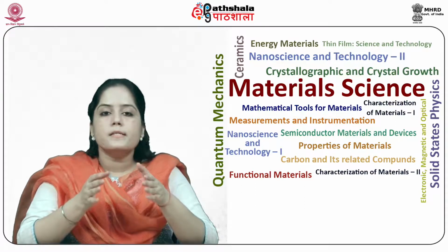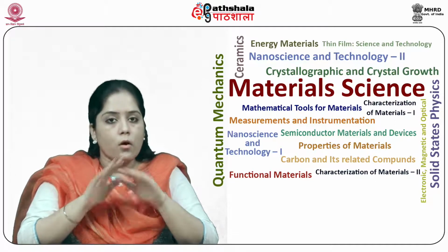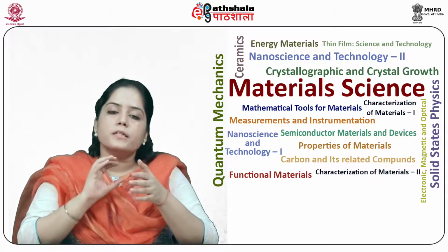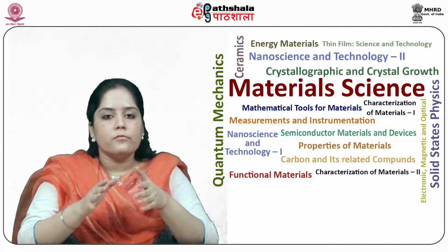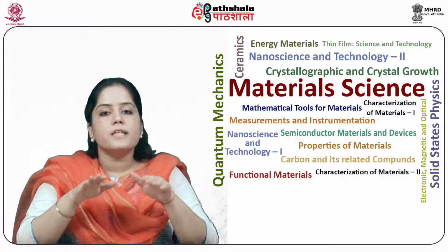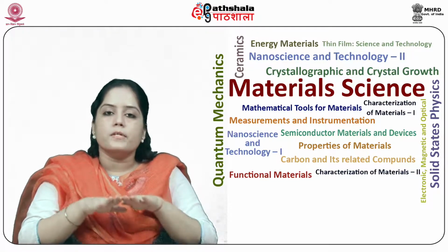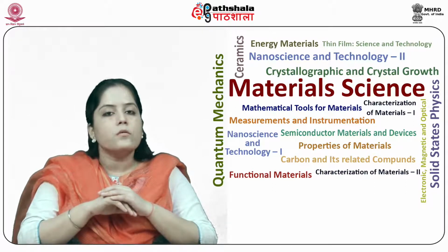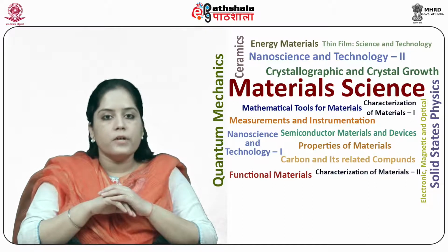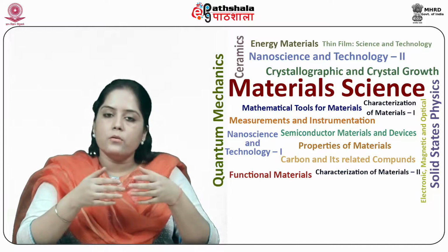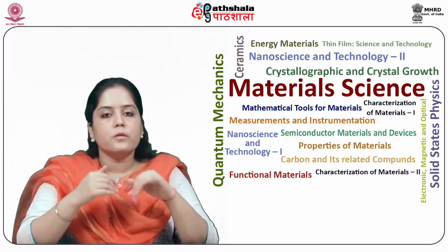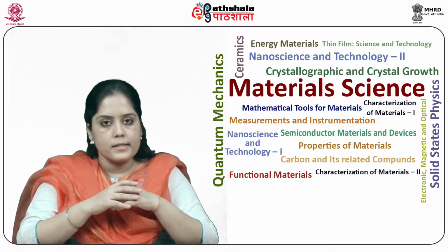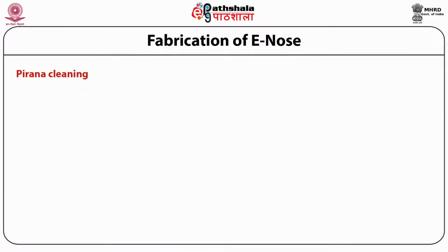This chemical sequence does not chemically react and attack the silicon. In fact, it removes the contamination that resides on the wafer surface. So, cleaning of the silicon wafer is carried out using a sequential process, which will be discussed in the later slides. Piranha cleaning.